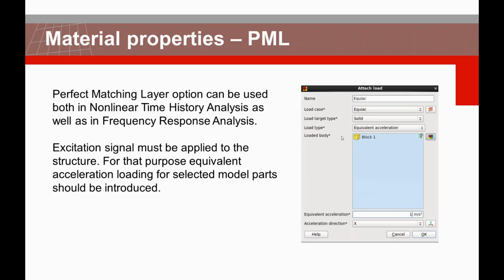In terms of the definition, as I mentioned, we need to assign this equivalent acceleration. The excitation signal must be applied to the structure, and for that we develop this equivalent acceleration loading, and you can assign that to the body. So this is very important. This should be assigned to the full model, not only to the corner, edge, or point.